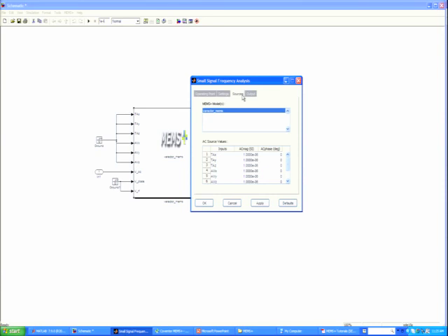The 1e minus 6, this is in SI units, is a good number to start off with. That's a good scale number. This has been historically accurate for all of our other tools, and it seems to work here as well. So start off with 1e minus 6. If there's a g force, if you drop the thing, you may have a higher number on z, and you would change that here. You may say 10e minus 6 or something like that. But for now, let's just run with this.